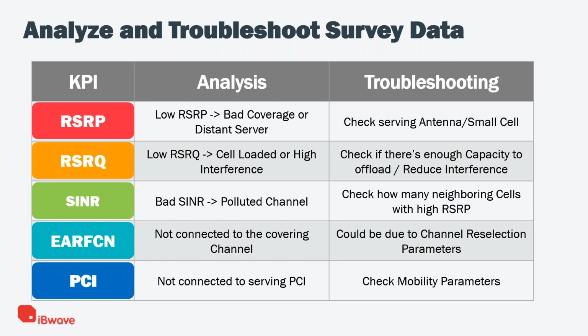Smaller area of coverage, low power, meaning less interference. Bigger area of coverage, maximum power. If the cells are close, then you get high interference. So big max power does not mean good. That's something I learned from my experience doing stadium designs, for example.